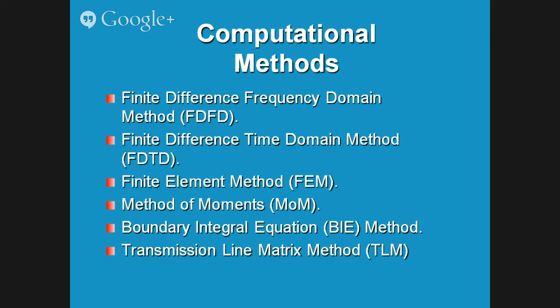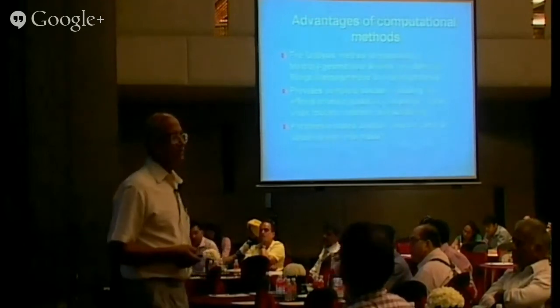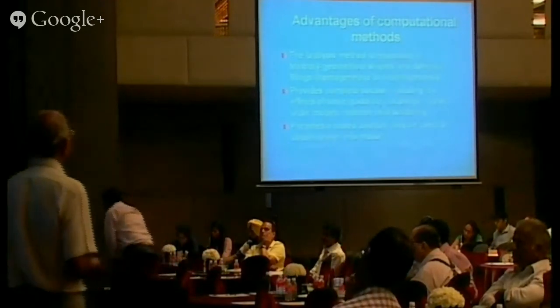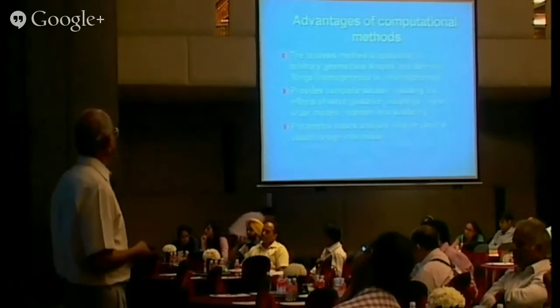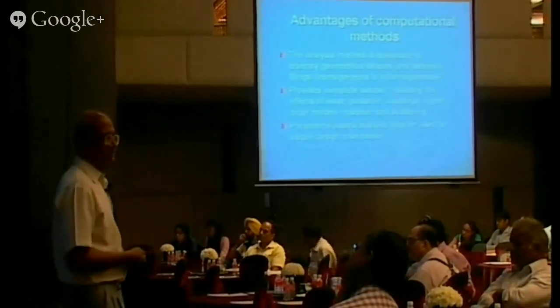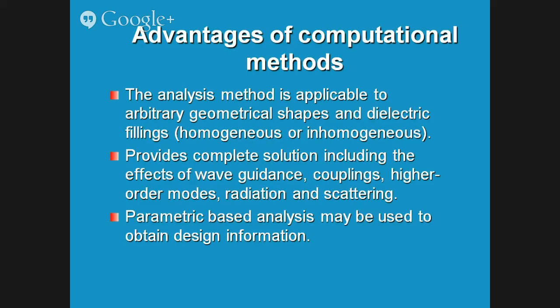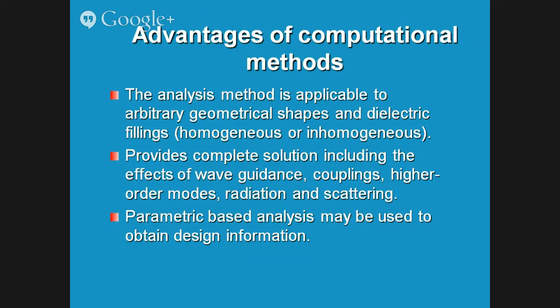These are a number of methods available, and these are the advantages: the method is applicable to arbitrarily shaped geometries and dielectric fields, homogeneous or inhomogeneous. It provides a complete, that is total, solution, including the effects of wave guidance, coupling, higher modes, radiation, and scattering. Everything is included in the solution process.